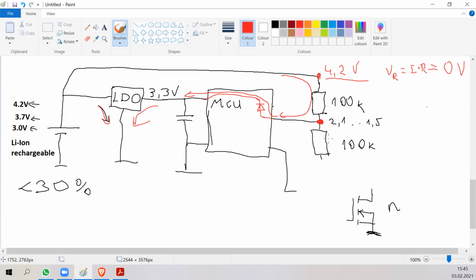And even though you think that you have disconnected this resistor divider, it actually starts to consume more. And I have seen this mistake many, many times. So you are absolutely correct. You need to cut off the voltage at the high end, not the bottom end, because from the top end, it will just leak through the microcontroller's ESD protection diodes into the supply.